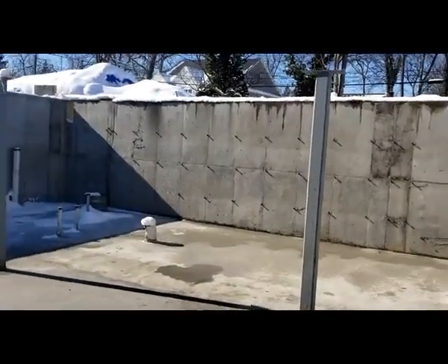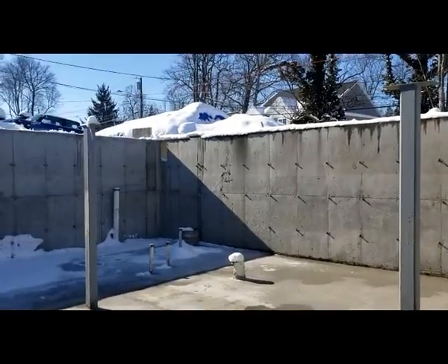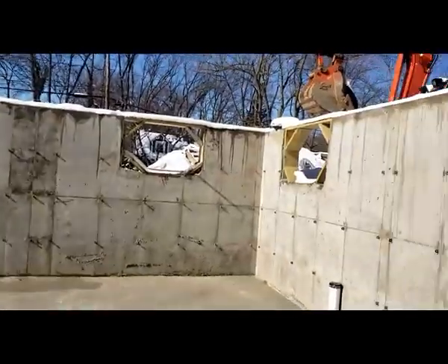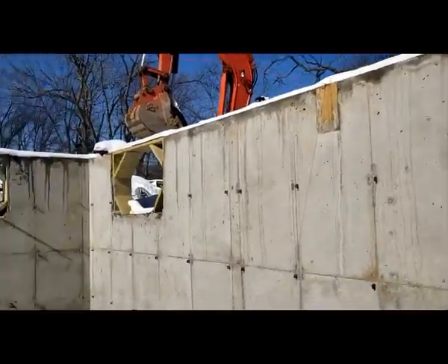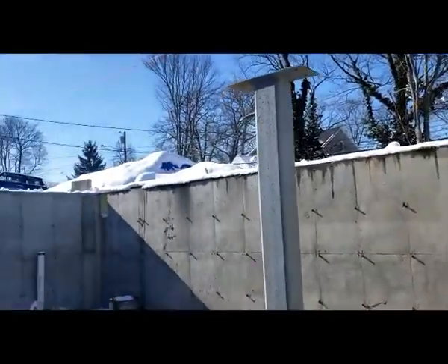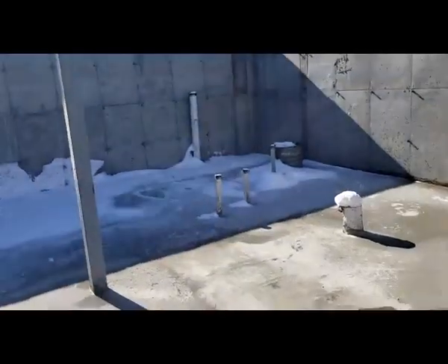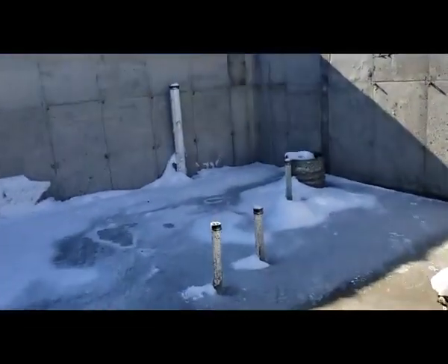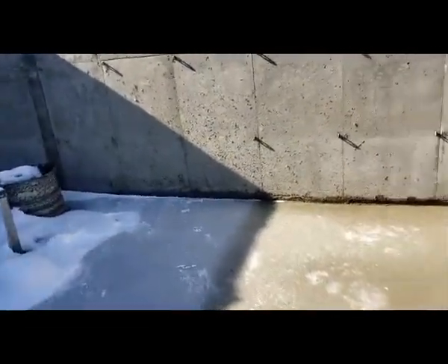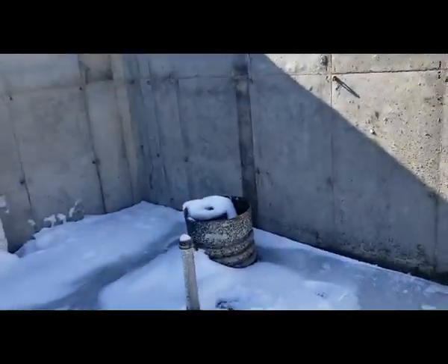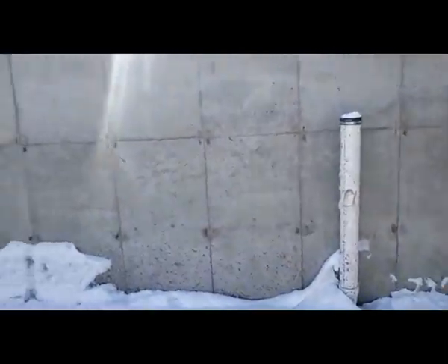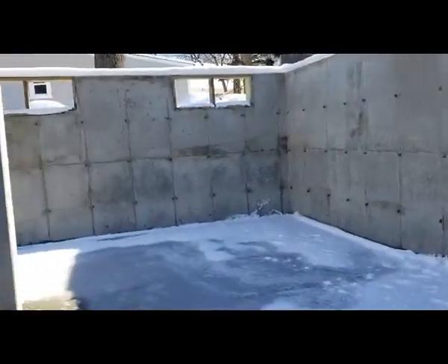And as you see, my columns are installed at the right elevation. I have the buckets inside the walls for the drop beam, I have all my windows installed. I have all my plumbing stacks. So I have one plumbing stack going up. I have a wet bar right in the basement. I have a toilet, I have the finish. I have the sump pump pit. I have all my plumbing run and ready to go before we pour the slab.